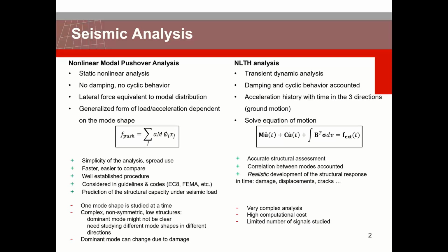And of course, this is a quite accurate structural assessment. It accounts for the correlation between different modes, and it gives us a realistic output of the development of the structural response in time, so in terms of damage, displacement, cracks. Well, the cost of this is that it is quite complex, so it comes with a computational demand, and because of this, the number of signals that can be studied in an analysis of a structure is quite limited.